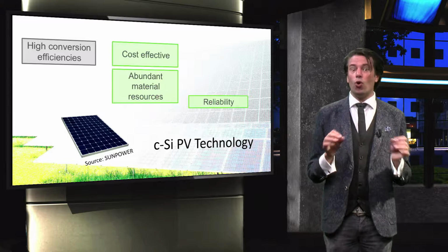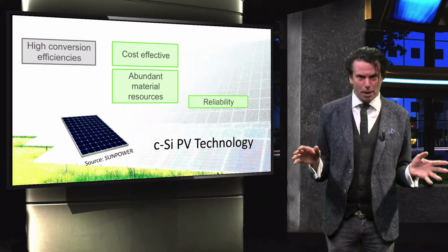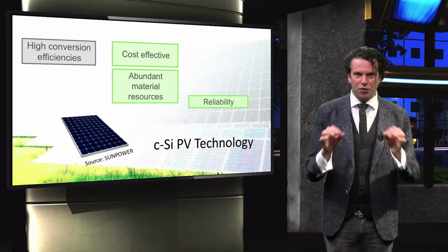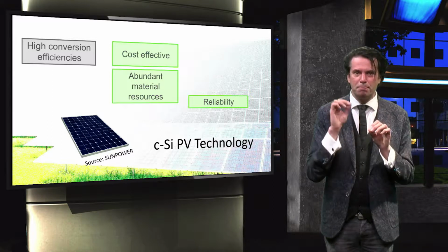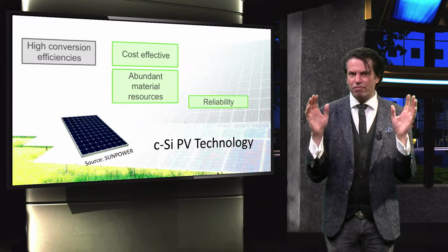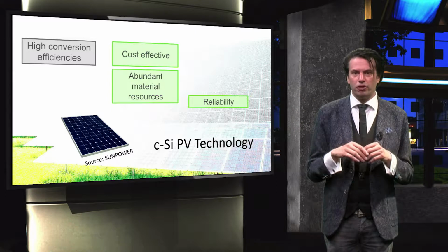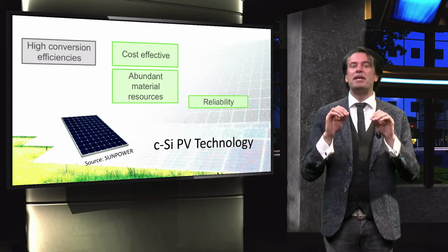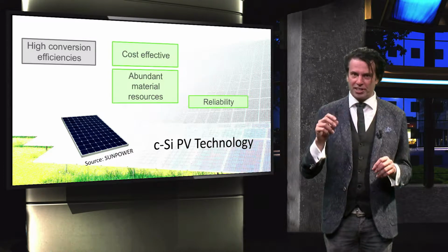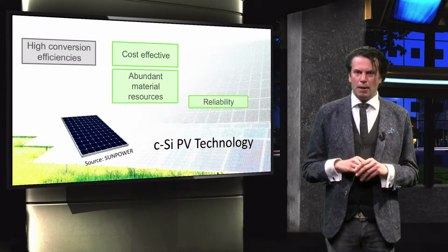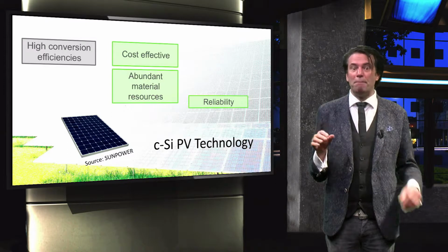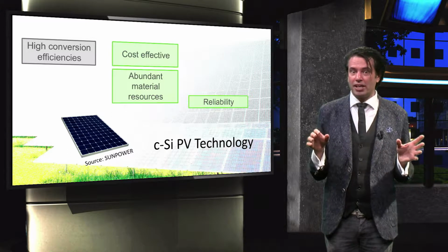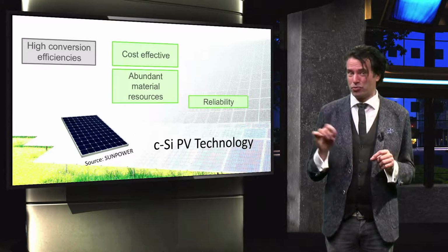Even in very old, poorly encapsulated crystalline silicon modules, the heart of the PV device keeps on working. The anti-reflection coating might have peeled off, but as long as the metal contacts do not peel off, the PN junction keeps on operating under light exposure. Many PV technologies are based on PV materials or supported layers like TCOs that are not resistant against water.